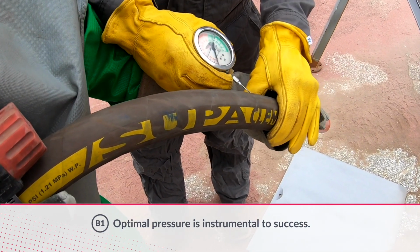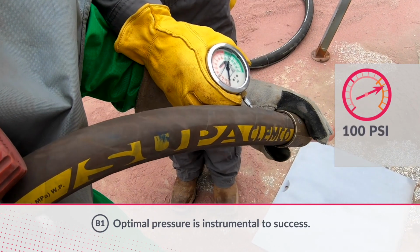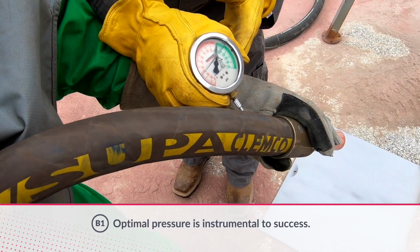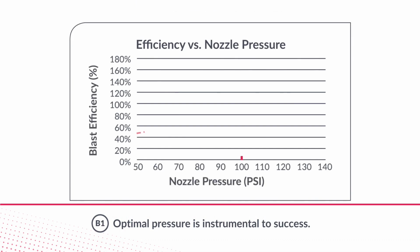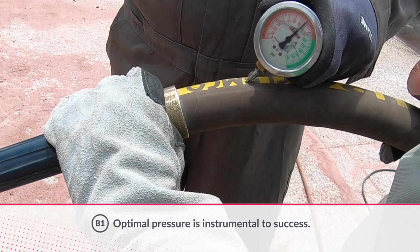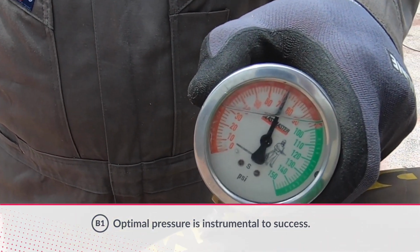To attain 100% efficiency, your nozzle pressure should be set at a minimum of 100 psi, no matter which nozzle size you use. Blasting efficiency drops 1.5% for every 1 psi below 100 at the nozzle. Efficiency increases as nozzle pressure level increases. If you are not achieving a minimum 100 psi at the nozzle, it's important to check your entire blasting system and locate the pressure loss.